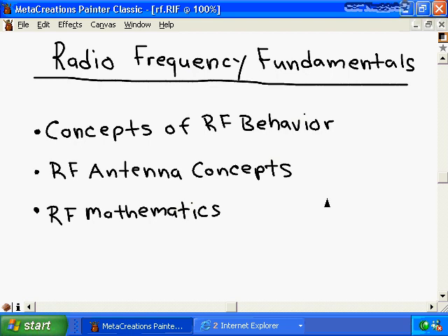So we started off this video by learning that a radio frequency signal can either lose or gain in its amplitude, and that the radio frequency can behave different ways depending on the obstacles or objects that it meets within its path. The radio frequency signal can be reflected, refracted, diffracted, scattered, absorbed. So for example, when a radio wave is refracted, that means that the radio wave is bending as it passes through a medium. In contrast, when it's diffracted, that's what happens to a radio wave as it bends around an object versus through an object.